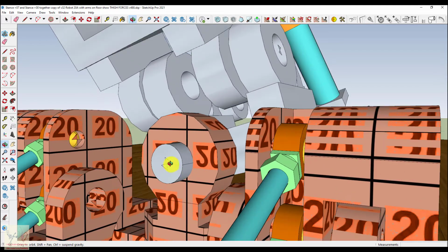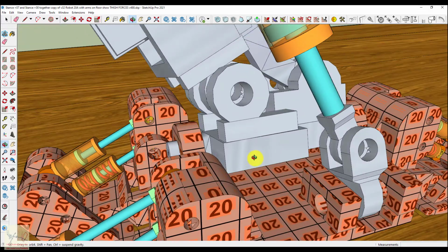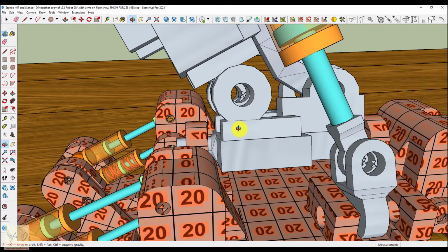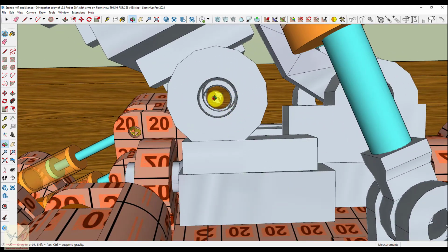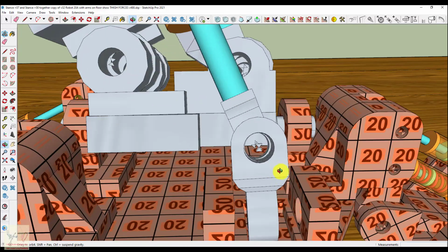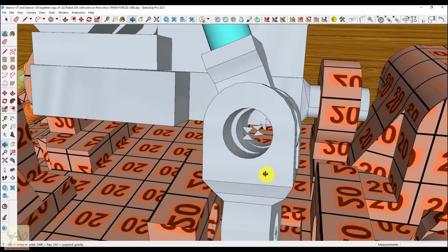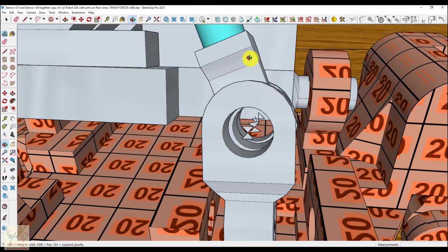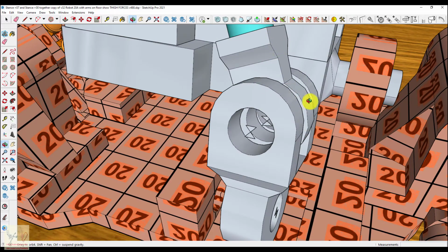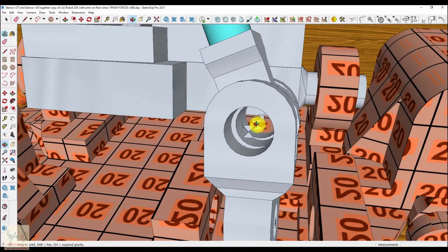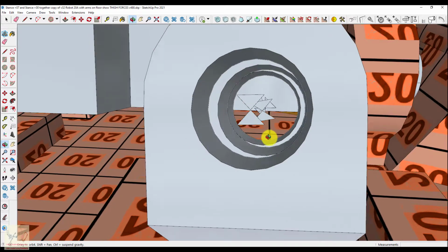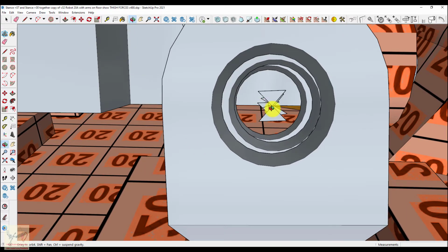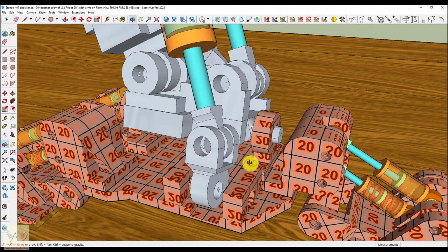I do have these little drawing points here throughout because when you're rotating these structures, you want them to rotate around the proper axis, and this helps to locate where that axis is. It's floating out in space here, and that's just to help to line it all up. Like here, this bearing has to be in between these two bearings, and so here is the little triangular drawing that shows where this bearing is, and so you can line these all up and show that this is pretty much lined up, and that's all that is when you see that.